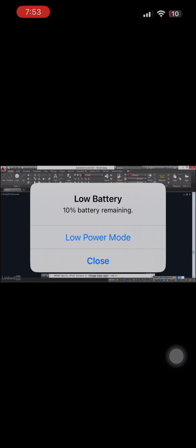Let's turn on Object Snap down here. Make sure you have Endpoint Snap selected and perpendicular. It says specify offset distance. Let's click this point and then move the cursor over a little bit until the perpendicular snap appears, and then click there. That has just input the wall thickness as the offset distance.